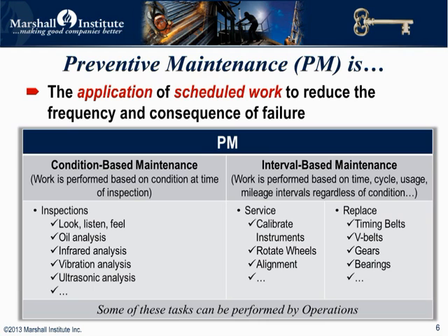Having said that, sometimes PDM is used to refer technically or specifically to high technology tools and instrumentation such as vibration analyzers, ultrasonic or infrared detectors, eddy current measurement, oil analysis, and so on. However, for the purpose of this program, condition-based maintenance simply means maintenance on the basis of condition or measurement.